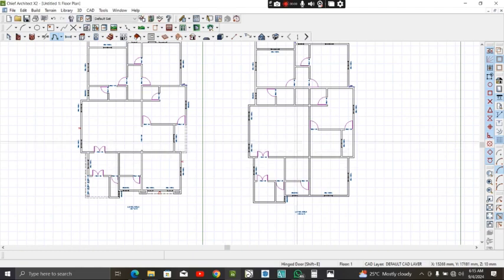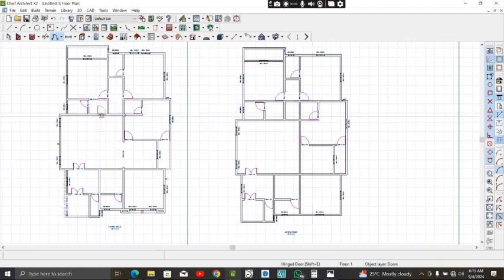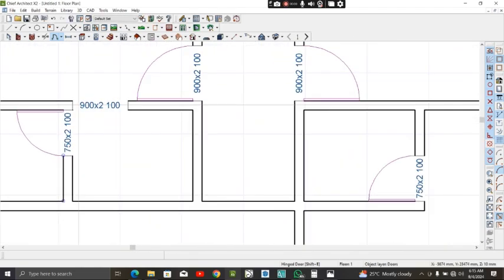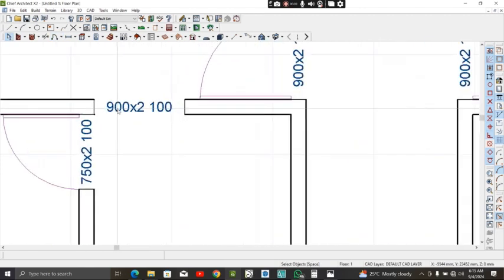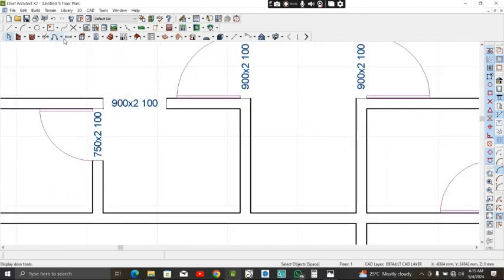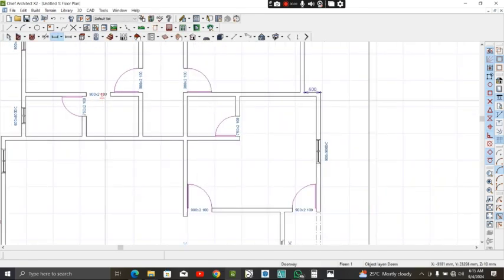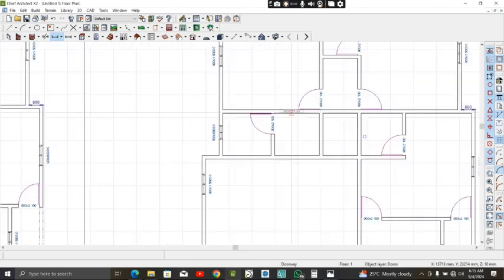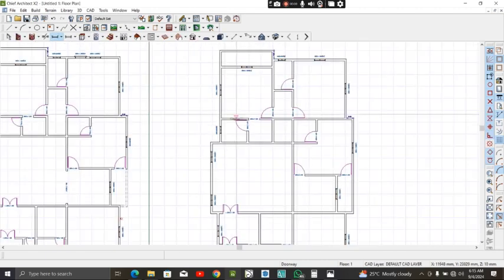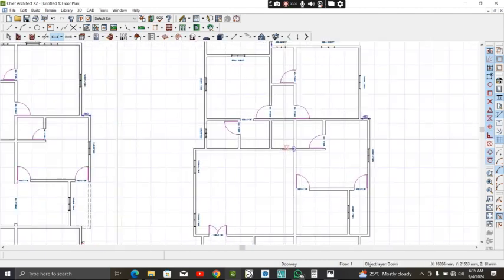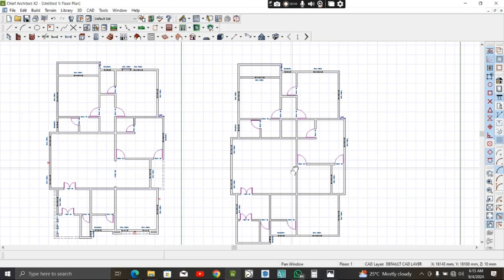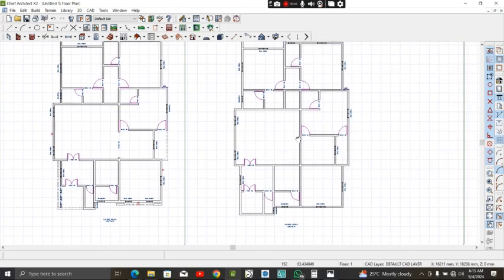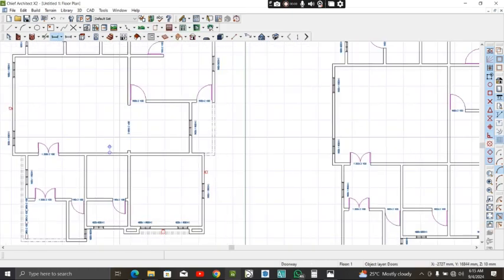I think we've placed the whole of our doors, but if you look at this point here, you are seeing something like a door, but it's not a door, it's actually a doorway. You can get it from this icon. You click doorway and place it here. It's an opening, but it's not a door. Just place it where we have those openings in the plans that we're using.